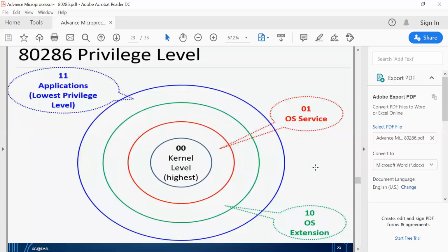Now, the privilege level: why do you need it? Because the 80286 supports a 4-level hierarchical privilege mechanism to control the access to descriptors, and hence to the corresponding segments of the task. The control of access to descriptors prevents unwanted or undue access to any of the code or data segments, or unintentional interference in the high privilege level task.